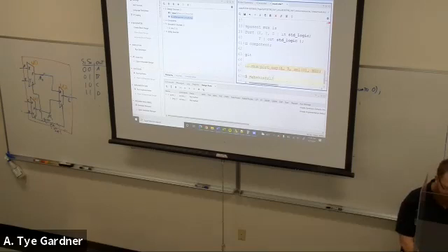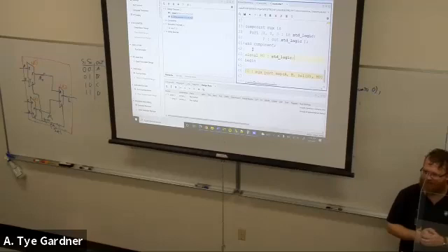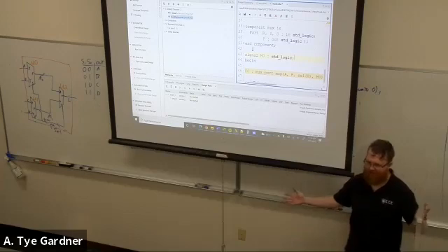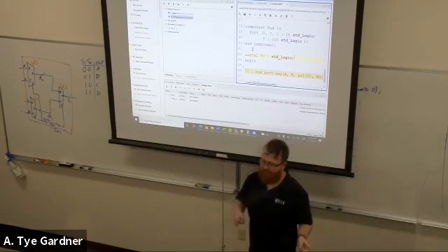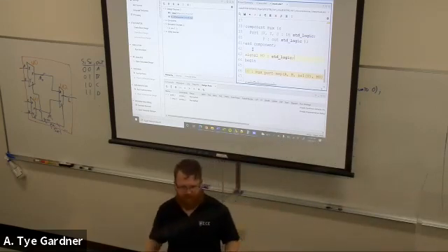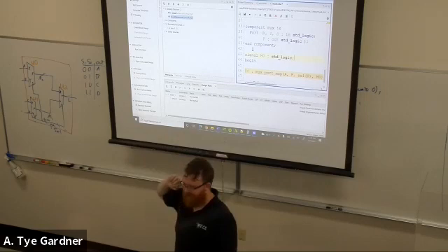Okay, it's going to be unhappy because I don't have an M0, right? So when I realize that I don't have an M0, I can jump back up and declare this signal, M0, standard logic. It's pretty standard to just make things as you need them, right? I've now declared my mux. I could go on, make the remainder, everything's fine. Okay, that's VHDL. Now, that's strictly combinational VHDL. Next time we'll get to sequential VHDL, things with memories, and I'll also introduce how I test this.